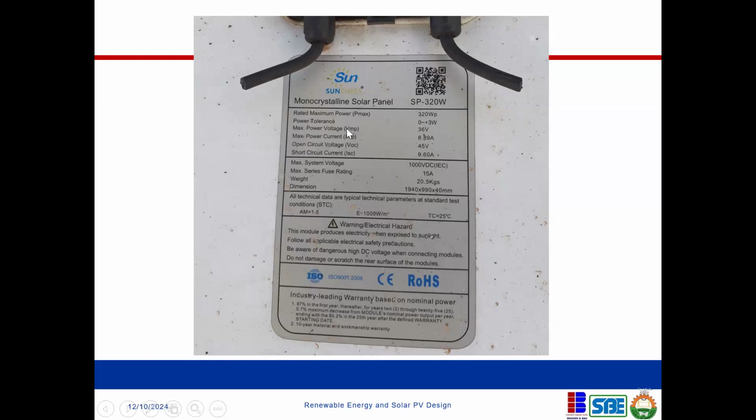You have the voltage at maximum power. That's what this means. The voltage at maximum power. No, sorry, that is OC. VOC means that when the current is 0, that is the open circuit voltage, right? Open circuit voltage is when the current is 0. Then this is your open circuit voltage. But this is your voltage at maximum power.